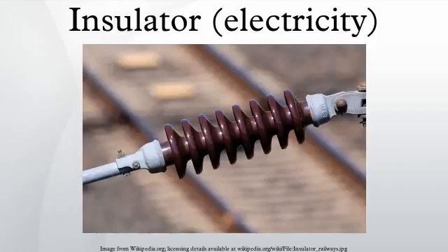In early days, the shackle insulators were used as strain insulators. But nowadays, they are frequently used for low-voltage distribution lines. Such insulators can be used either in a horizontal position or in a vertical position. They can be directly fixed to the pole with a bolt or to the cross-arm.